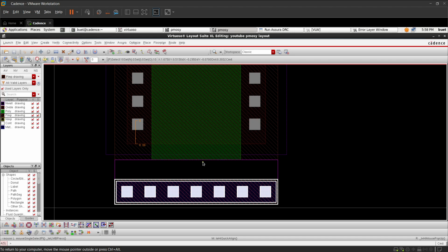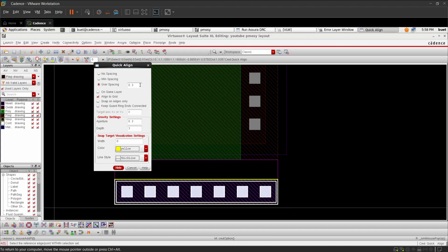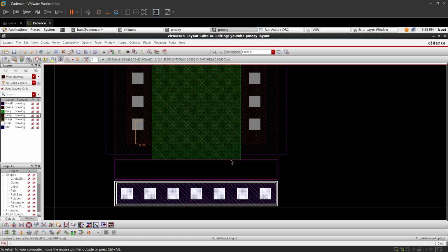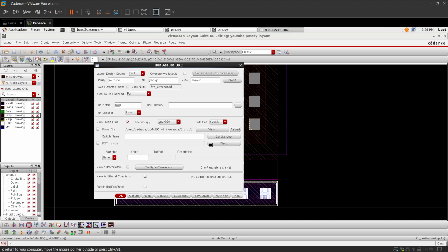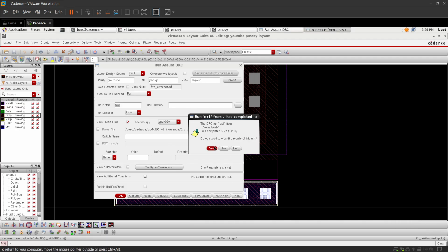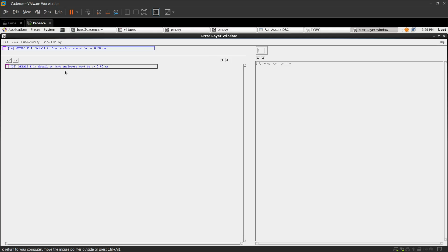at 0.24 distance only. Over here, make it 0.24. It's done. Okay, hopefully we are not supposed to see any error further, but we'll see. If any arises, we are supposed to resolve it. So this is what the analog layout design engineer used to do. They used to keep on debugging the errors that arise while doing the layout. So yeah, we have got rid of all these errors.